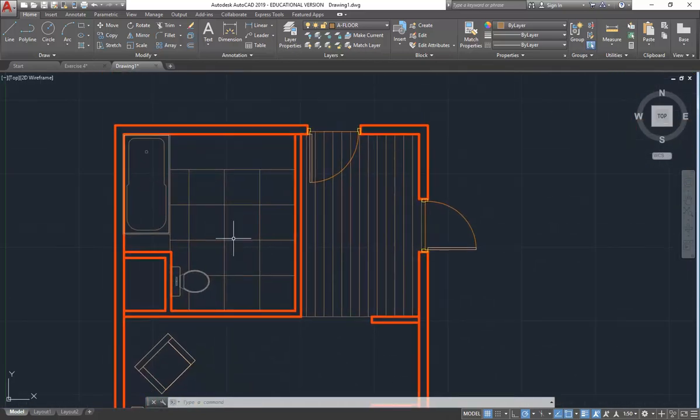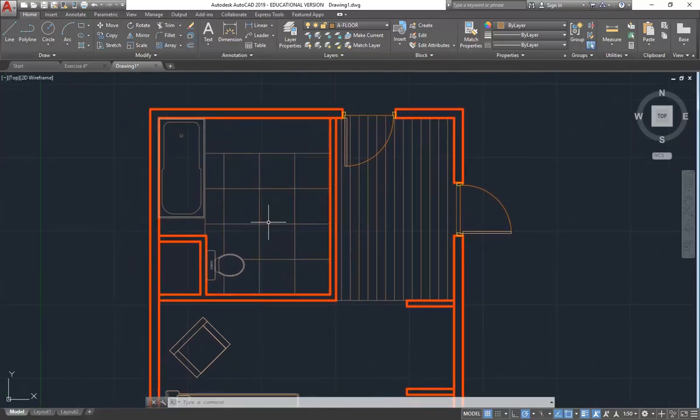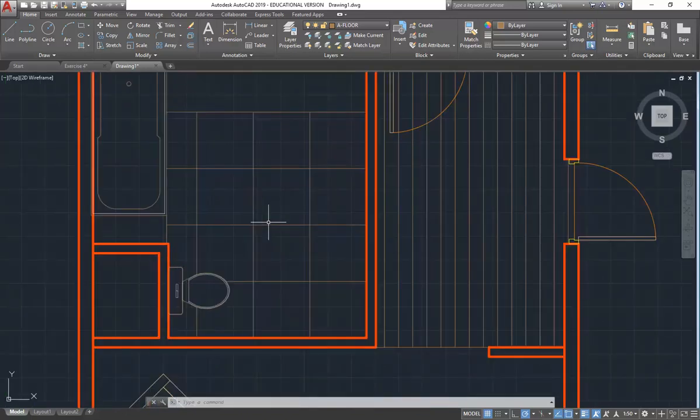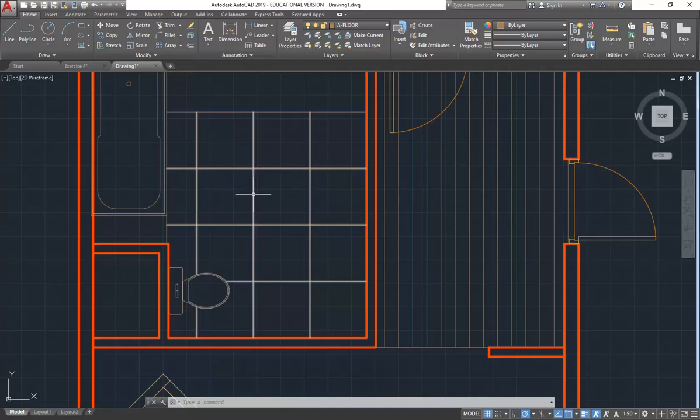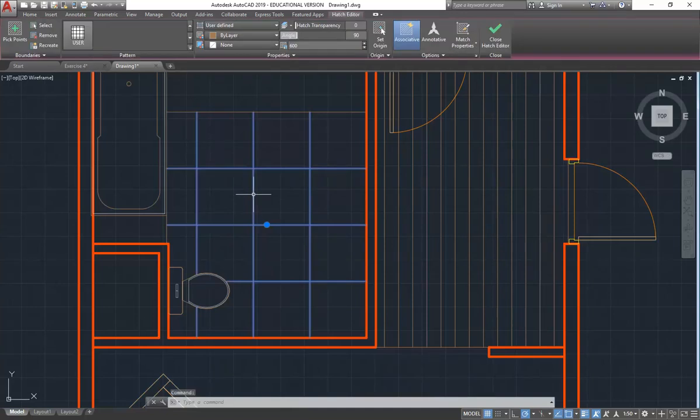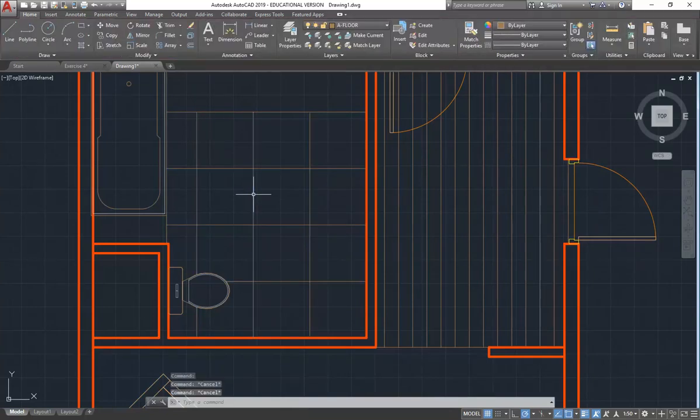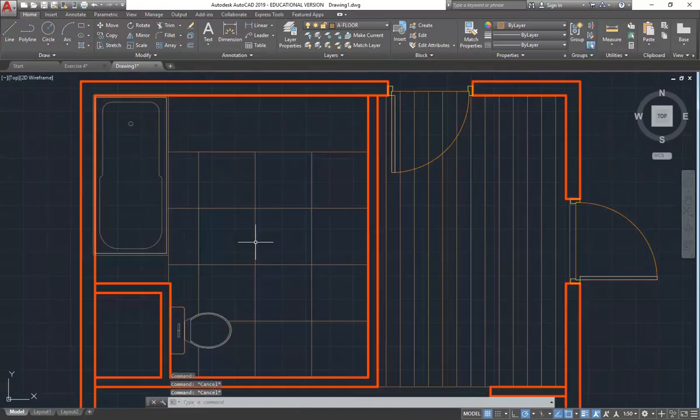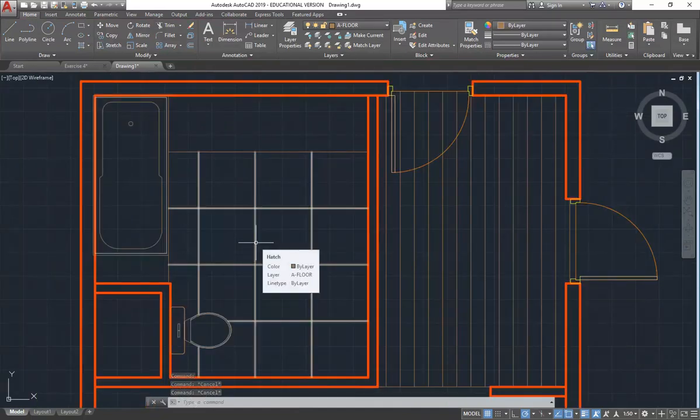Oh, one last thing. If you do want to change your hatches, I've got to put the door in, but I'll do that later. Say you decide, well, let's say it's a specific bath, and it's just a hatch that doesn't look like that bath. How do you import that? Oh, you need to make your own block. If it's one that you can't find, Caroma and Kohler and a lot of the big bathroom manufacturers make all of the things they produce available as AutoCAD blocks.